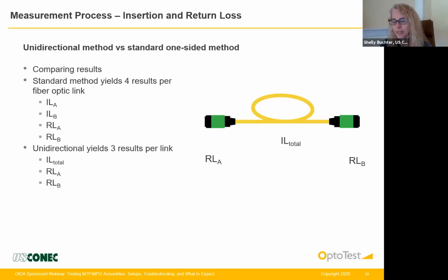As far as any questions on the MTP/MPO polarity changing, it takes thousands of cycles to change the polarity key within the MTP/MPO and still be functioning. It's a very easy process, one step with the tool, and provides a very quick ability to check and verify your polarity on the MTP/MPO connector.